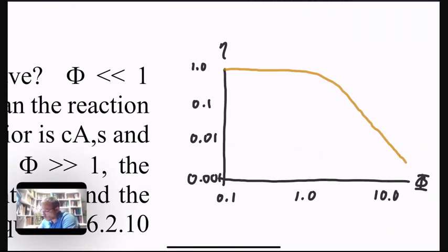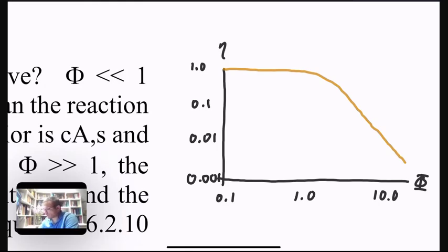Of course, it goes to 1 when the Thiele modulus is very small, indicating that there are no diffusion limitations. But also, there's a convenient expression when the Thiele modulus is very large, and that's that it asymptotically approaches this 3 over phi limiting behavior. And in many cases, that is a really useful thing to keep in mind. It's easier to work with than the cotangent hyperbolic expression when you know that you have severe diffusion limitations.